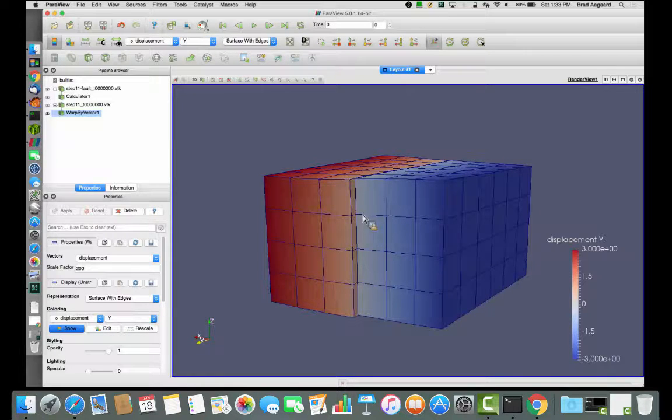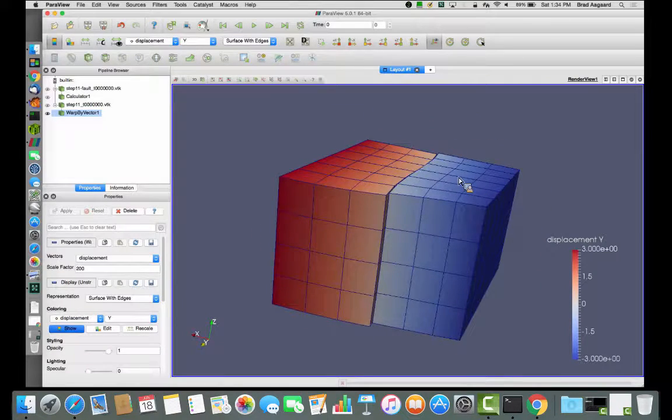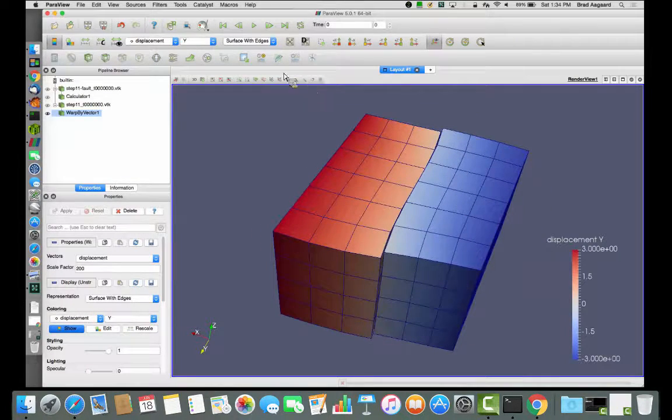The reason why the ratio of the shear stress in the along-strike direction divided by the normal stress was not 0.6 at these corners is that there's some shear stress in the vertical direction. So the shear stress in the plane divided by the normal stress is equal to 0.6 at those locations. Any questions about this example?